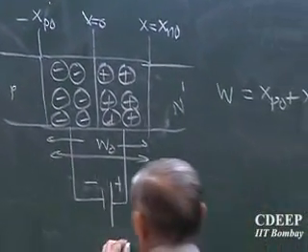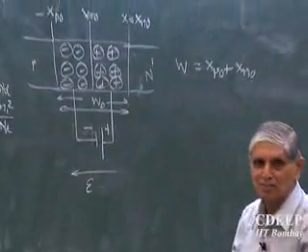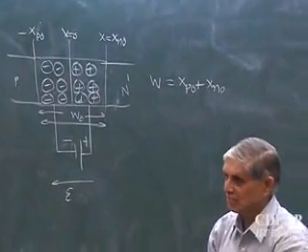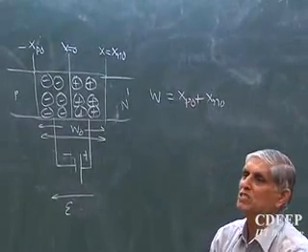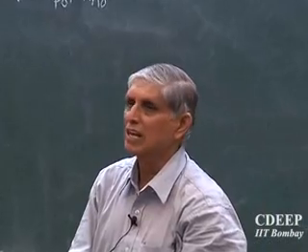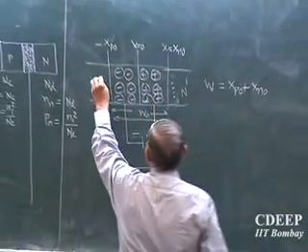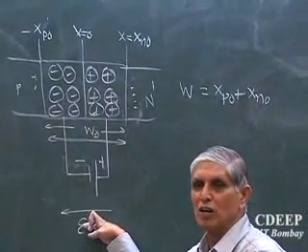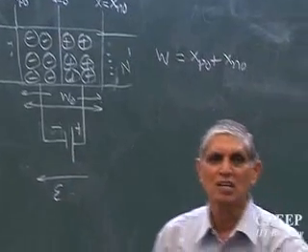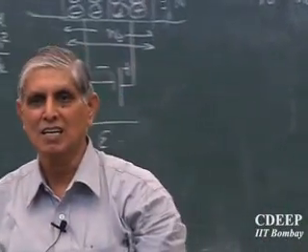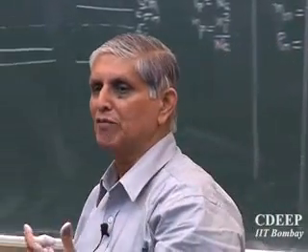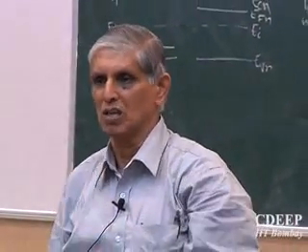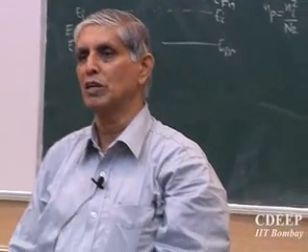This battery creates an electric field in which direction? Positive to negative. Is that correct? Holes move in which direction with respect to the electric field? The same direction as the electric field. Electrons move in the opposite direction. So now these electrons which are here and holes which are here, can they go across? This electric field will not allow additional holes and electrons to diffuse through. Is that clear? This field is therefore called the built-in field, or V0, or total potential. Built-in potential or built-in field, which it creates.